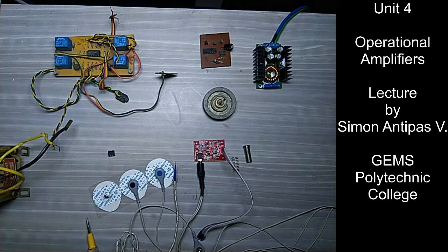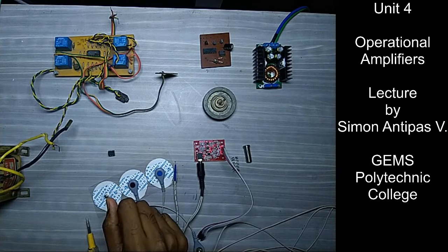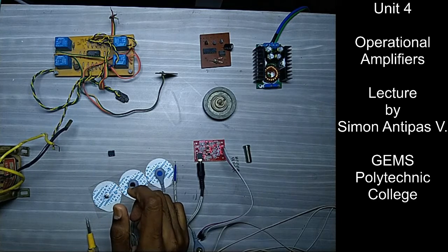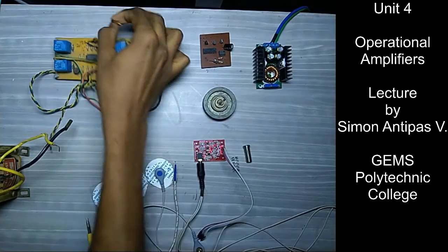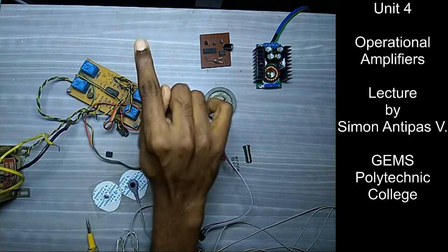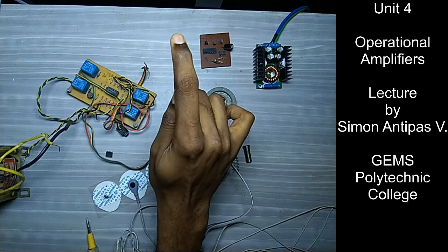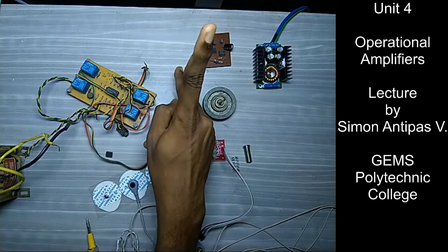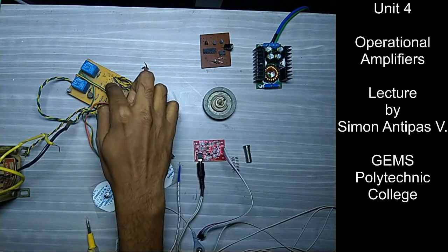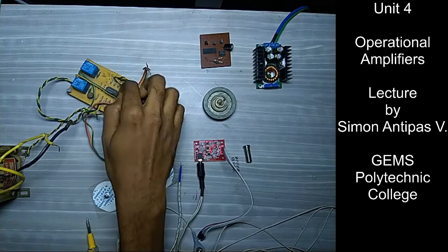And why do I need to have op amps? For example, I need to measure the resistance of water and turn on a pump. How do I detect water levels? One of the simple methods is using wires as electrodes. I stick one electrode right into the bottom of the tank and one electrode on the surface of the tank. When the water level comes up, it touches that wire. I can measure the resistance of the water. And the moment I see the resistance, there's a small current that could be considered as an input, and that could be used to turn on an op amp.